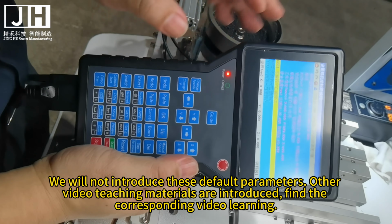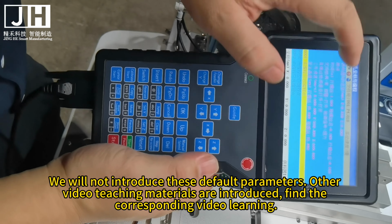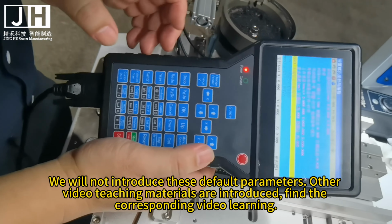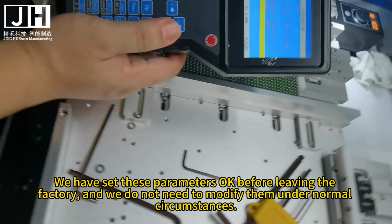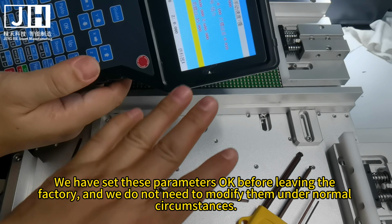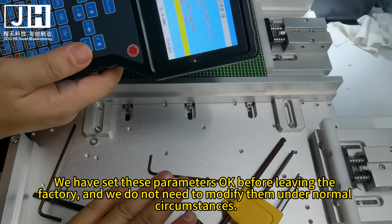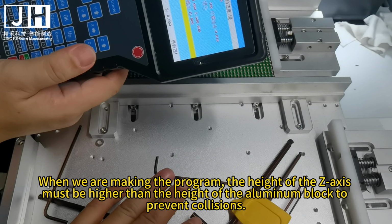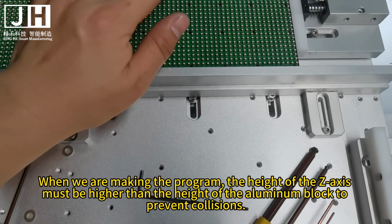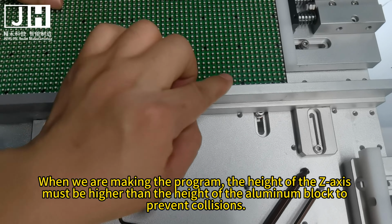We will not introduce these default parameters. Other video teaching materials introduce them; find the corresponding video to learn. We have set these parameters before leaving the factory, and we do not need to modify them under normal circumstances. When we are making the program, the height of the Z-axis must be higher than the height of the aluminum block to prevent collisions.